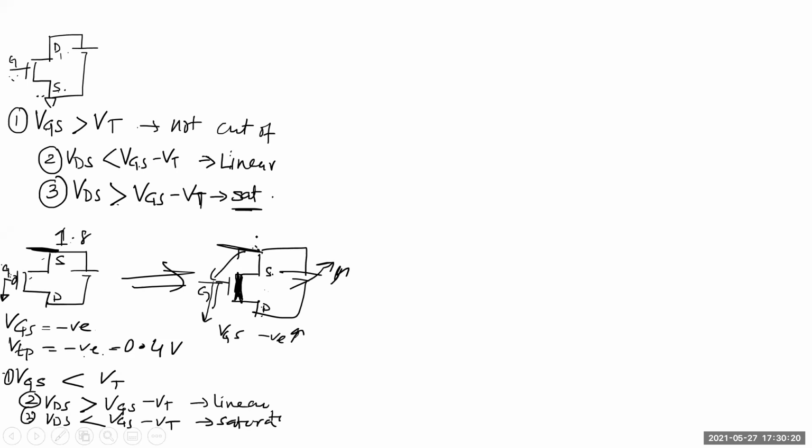And if it is all confusing you, like I said, take VSD and VSG instead of VDS and VGS, because this is really your reference node right now, right? So if you take VSG, this is your reference node, but it's a higher node. That's why everything is turning to be negative. So you take VSG, then everything will turn positive again. You have to take mod of VTP, or take all mods, VGS mod, VDS mod, VTP mod, and follow this three. That'll work also. But find one, stick to it, and just use that.